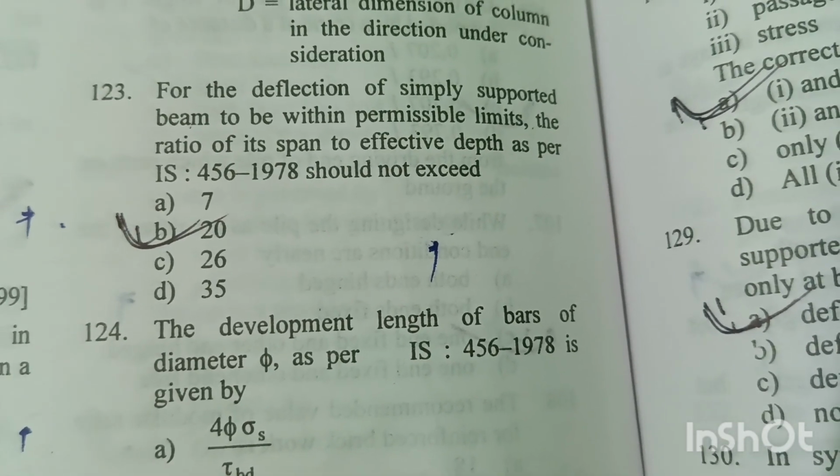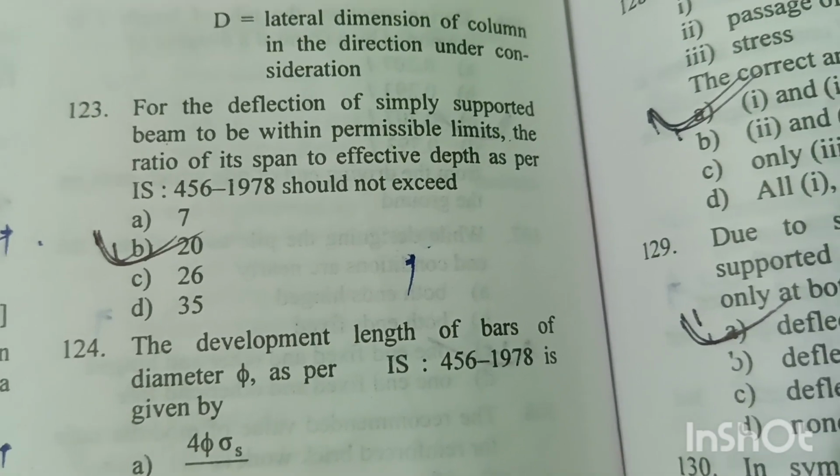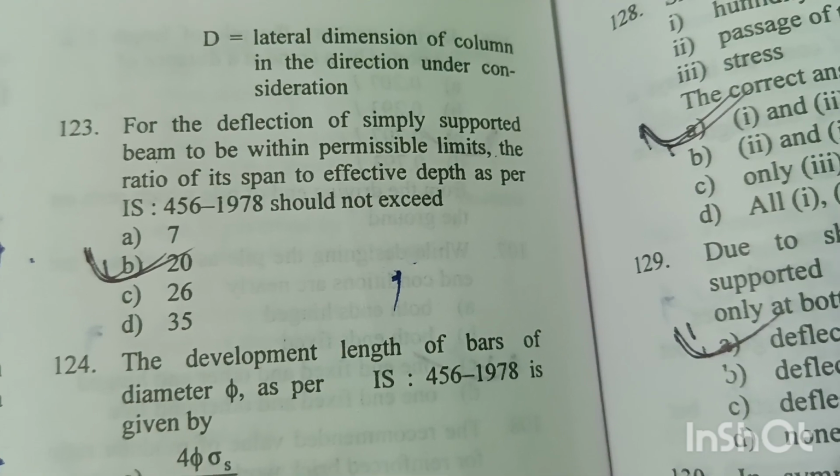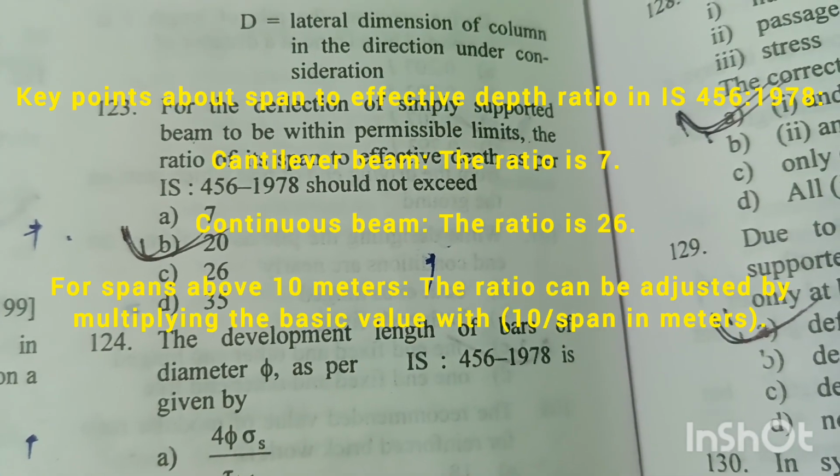For the deflection of the simply supported beam to be within permissible limits, the ratio of its span to effective depth as per IS 456 1978 should not exceed 20. Option B is right answer.